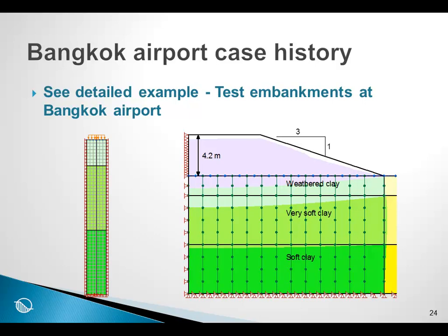Let me re-emphasize, I would strongly urge you to model one cell before you go to the actual field case. And when you go to the actual field configuration, I would strongly urge you to start with simulating the drains with a boundary condition along a geometric line, and not to model the wick drain with actual interface elements.